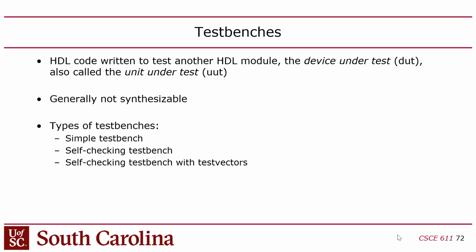And so the idea with test benches is that you write Verilog code that's designed to be run in the simulator, but never intended to be synthesized. And for that reason, Verilog has things that you can put in your code that are not synthesizable, right? Things that are intended just for simulation, like, for example, print, right? You can put a print statement in Verilog, and it'll print to the console when you simulate it, but obviously you can't print if it's on the FPGA, right? I mean, at least not directly from the hardware. You have to have a whole serial console infrastructure to print something, right?